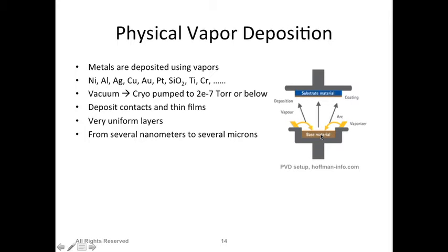and make vapors, and then those vapors evaporate, and you have your substrate where you want to deposit a film on the top. These vapors will go and bind on the top surface and start depositing. Sometimes you have to use some other adhesive layer to promote adhesion, but normally these vapors stick very well with most of the substrates we use, like silicon dioxide, glass slides, or any other, let's say, plastic sheet. So they stick pretty well. This is very simple and straightforward.